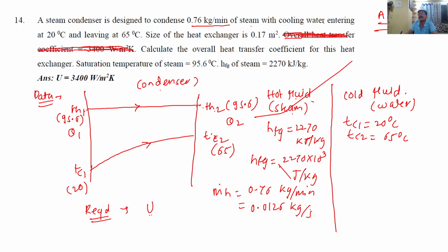The very first step is you need to calculate CH, the heat capacity of the hot fluid. It is the product of m dot h into Cph. The heat capacity of the cold fluid is the product of mass flow rate m dot c into Cpc. So let's do it. What is m dot h? m dot h is given as 8.4 times 3.